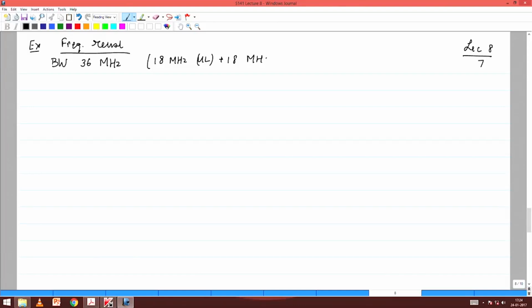Okay, the total allocation has to be taken into account, that one half of it is uplink, the other half of it downlink. So, this is a frequency division duplex system. Now, each user is using 25 kilohertz, and basically one channel per user is what we are doing. One channel per user. Such a system would be called, what type of multiple access am I using?